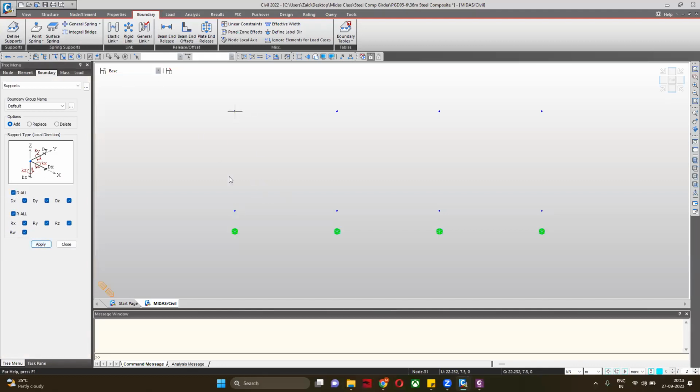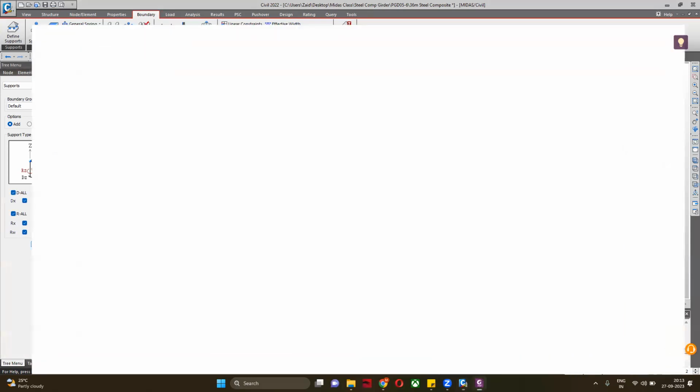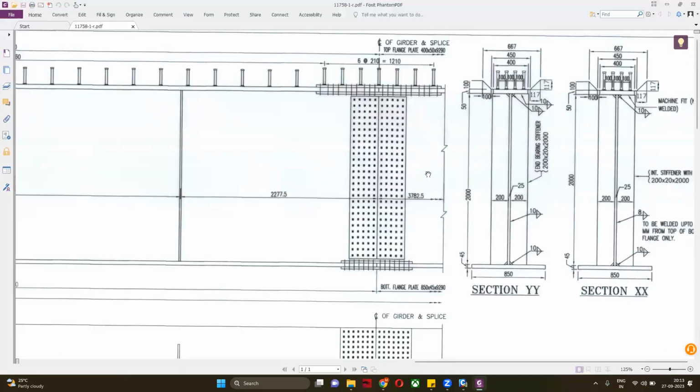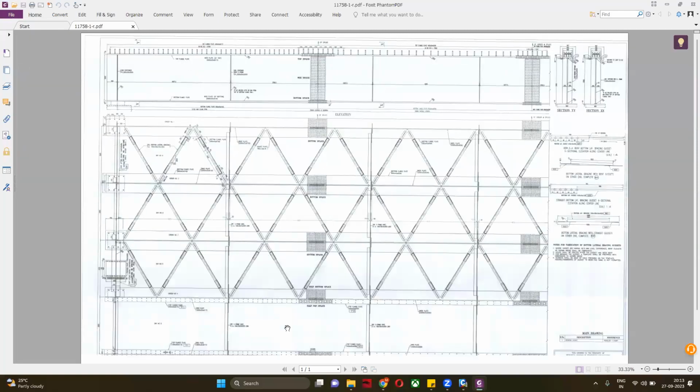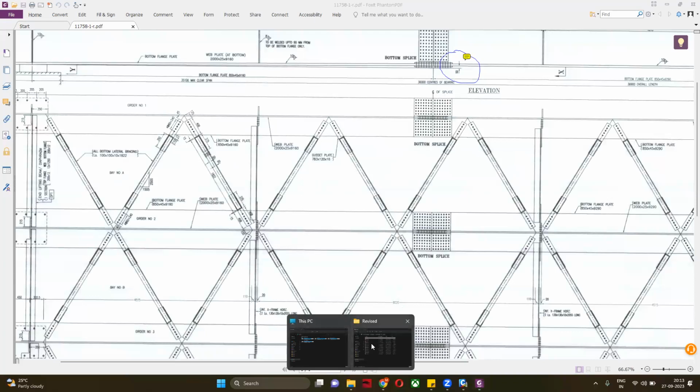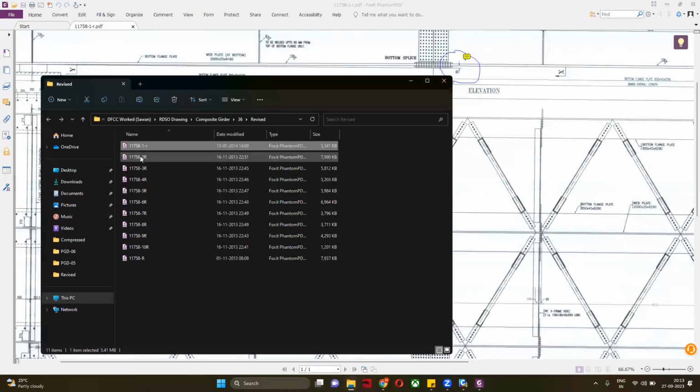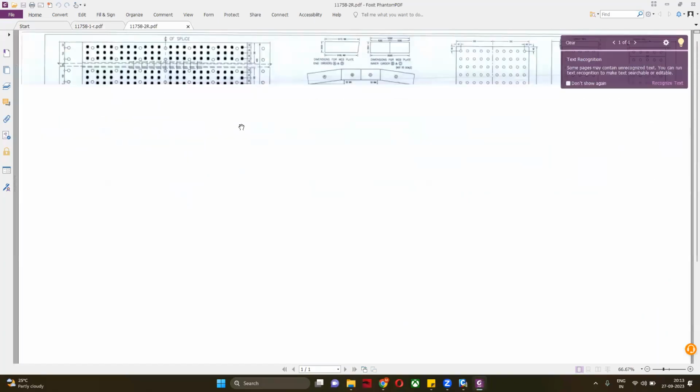Now, before joining these, first of all we need to provide the bracing point also. Because all the things are going to be connected in this portion, we do not require a bracing point. We can directly connect the end diaphragms because at the end girder we do not have any bracing. At this location, we have a diaphragm available, so we can see the end diaphragm properties also.